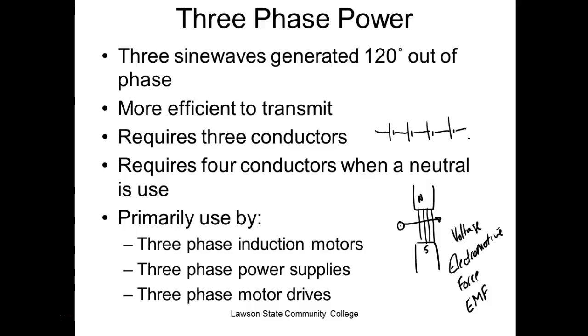The voltage adds, right? If this was 1 volt, and this was 1 volt, and this was 1 volt, and this was 1 volt, then I would get 4 volts. I would measure 4 volts when I whip that wire through there. But it has to be cutting the field. So when it got on this side, it would be 0 volts, right? You understand?